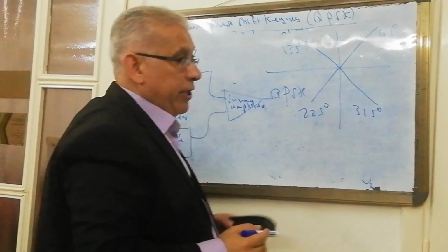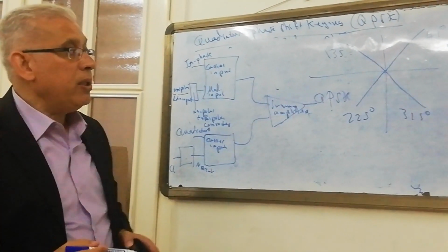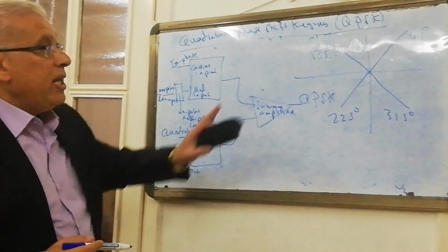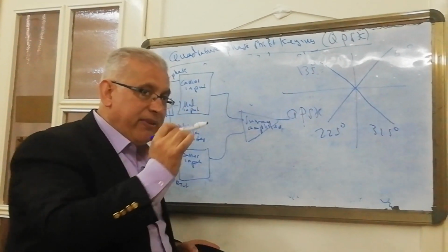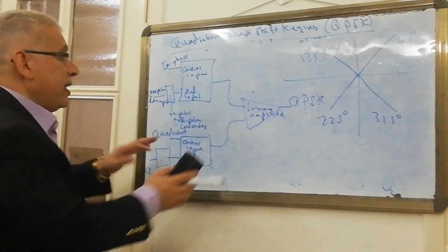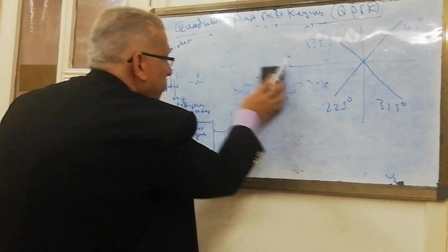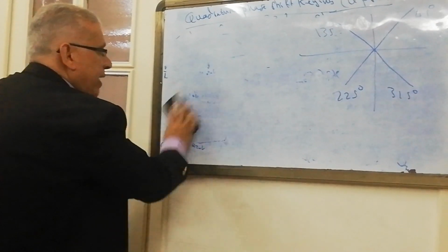So we have 4 interpretations for the angle, and only one of them is correct. In order to solve this problem, we will not assign the phase itself; rather, 00 means a specific change in phase compared with the previous one. This modification solves the problem we call phase ambiguity.